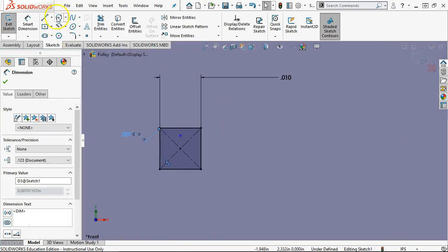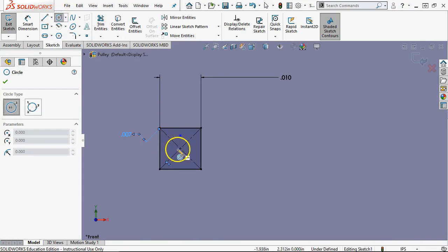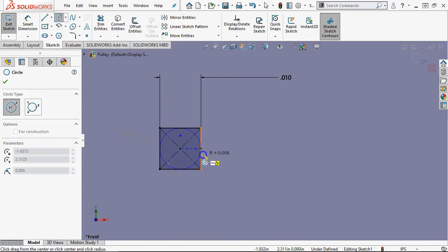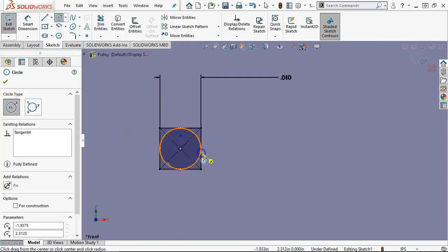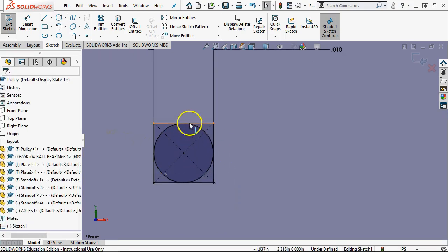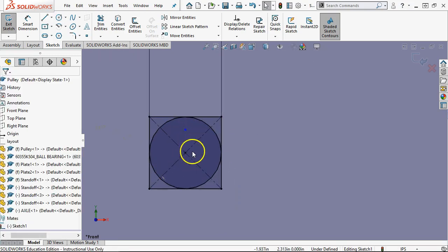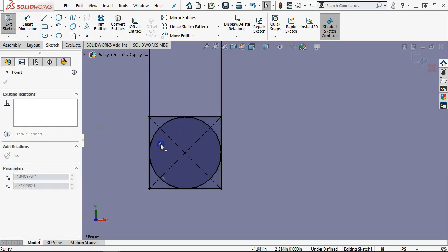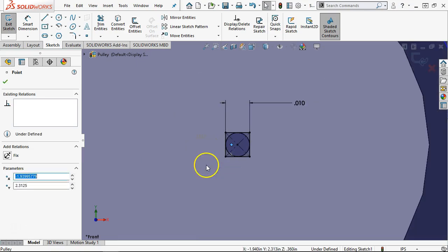All right. So on the circular tolerance, we're pretty much saying that if I go 10 thousandths, and that just came up tangent, it's either going to be, we're going to fit completely within this plus or minus 5 tolerance, or as our tolerance gets tighter, 2.5 thousandths plus or minus. But we can't stray outside of the circle into this second range with our position.